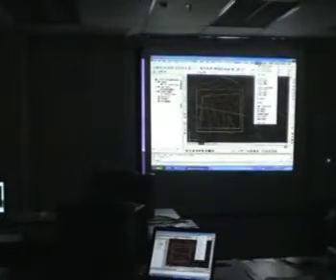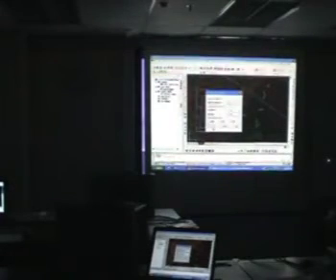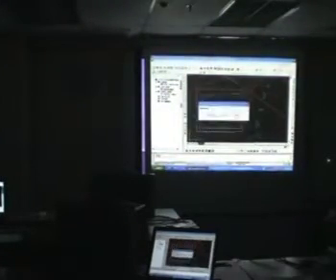Okay. Now we've defined our original and our proposed level. We've defined our site. Now to run the calculations for grid, it's very easy. You just need to pick calculate total site volume. Select the site. Here is where you can apply any volume correction factors if you need to. In an actual project, usually for fill factors, you must put a little bit higher. You have to take into account that whatever soil you import is not necessarily how much is used to fill. You have to take into account the compaction and the settling. So let's say it's 20%. I'm going to put, say, 1.2. Of course, you can always adjust that later.